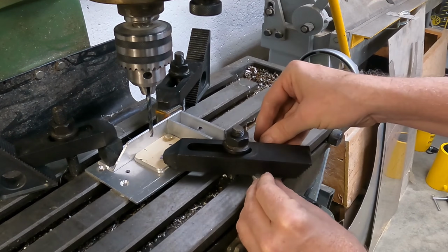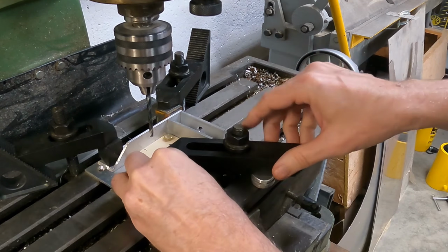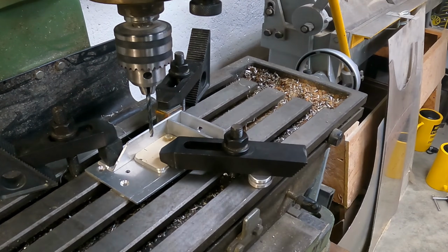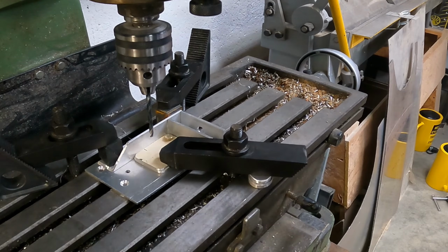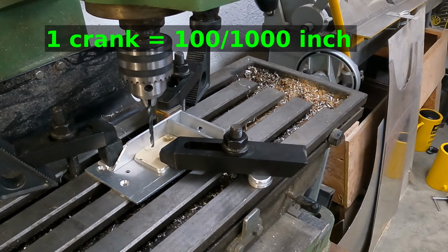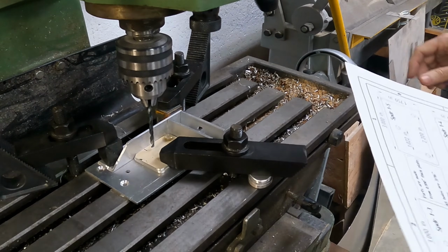And then I'm going to crank this table in the X direction over to where I need to drill the second hole. Now you can't see it here, but the crank has a mark every 1/1000th of an inch. So I just need to know how far to crank it around, how many times around. One complete revolution of the crank is 1/100th of an inch. So I need to know how many hundredths I need to crank over, and then how much of a portion of crank I need to rotate to get to that second hole.